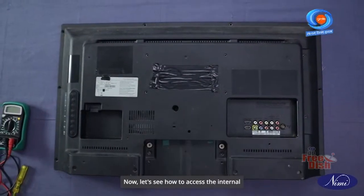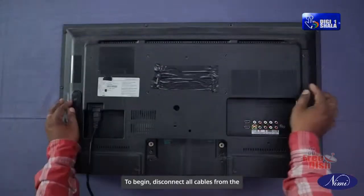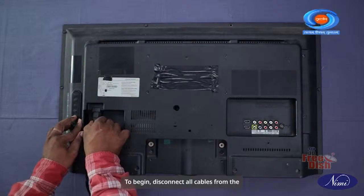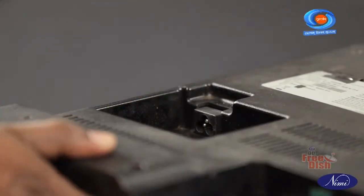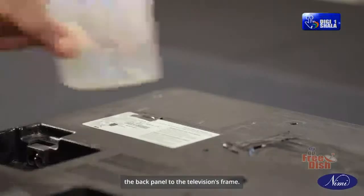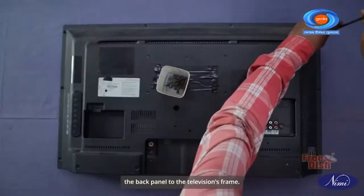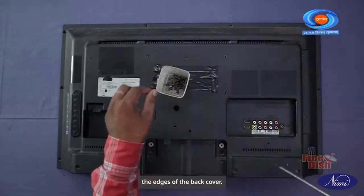Now, let's see how to access the internal components of the TV. To begin, disconnect all cables from the television and proceed to remove the back panel. Locate the screws or fasteners that secure the back panel to the television's frame. These are usually found along the edges of the back cover.